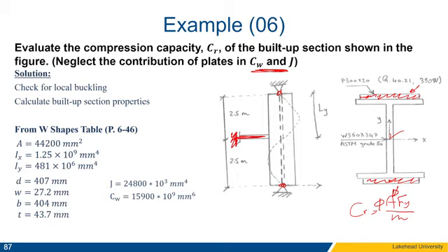Now, if I draw the I-beam in that shape, and we have some dotted lines like that, do we expect the I-beam to look like this or like that? Obviously, it would be similar to option 1, but not option 2, because we have those dotted lines representing the web over here. In that case, we understand that this will be the orientation of our I-beam.